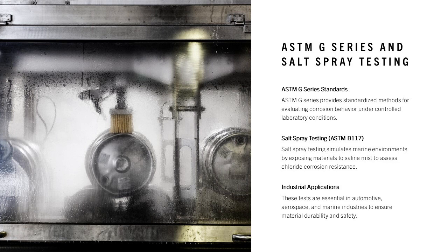Salt spray testing, ASTM B117, simulates marine environments by exposing samples to a saline mist, assessing their ability to withstand chloride-induced corrosion. These tests are widely used in automotive, aerospace, and marine industries to ensure long-term durability and safety.